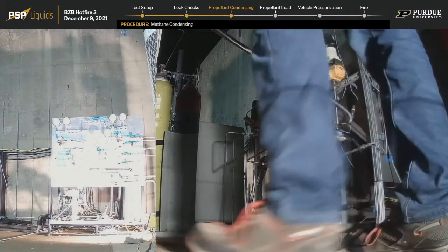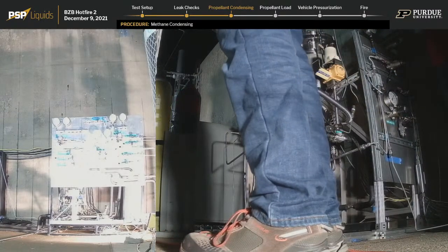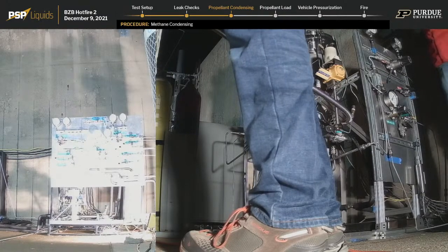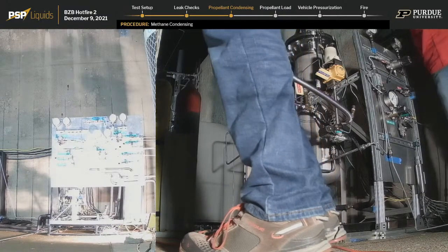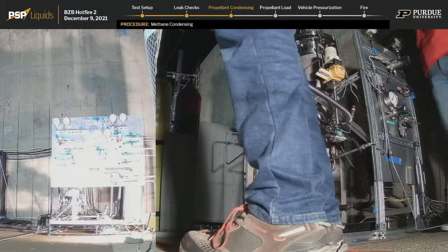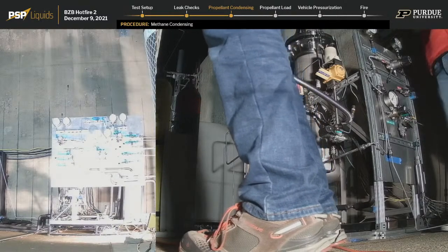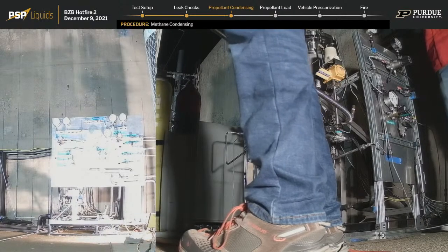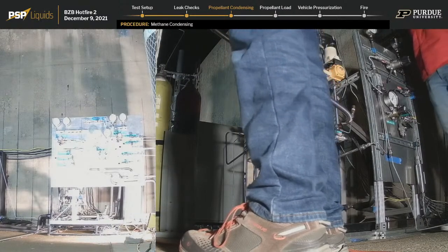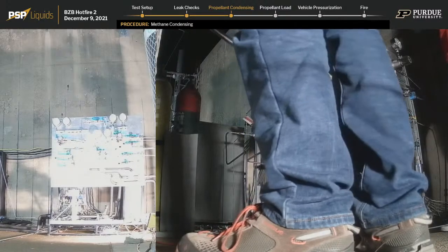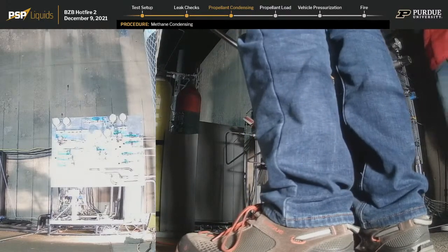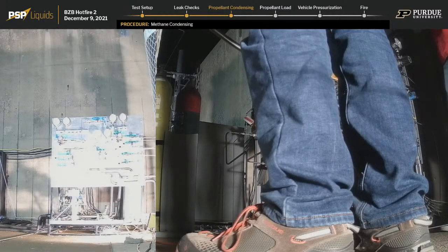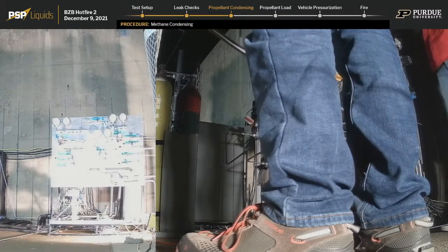What would happen if that's the liquid valve? So, if we froze methane in the system, this would be really bad. We do have filters within the system to catch any solids, but in the eventuality this does get into the rocket system, this could really mess things up by clogging an injector port, or say our cavitating venturis, and restricting the amount of flow that goes to the engine.